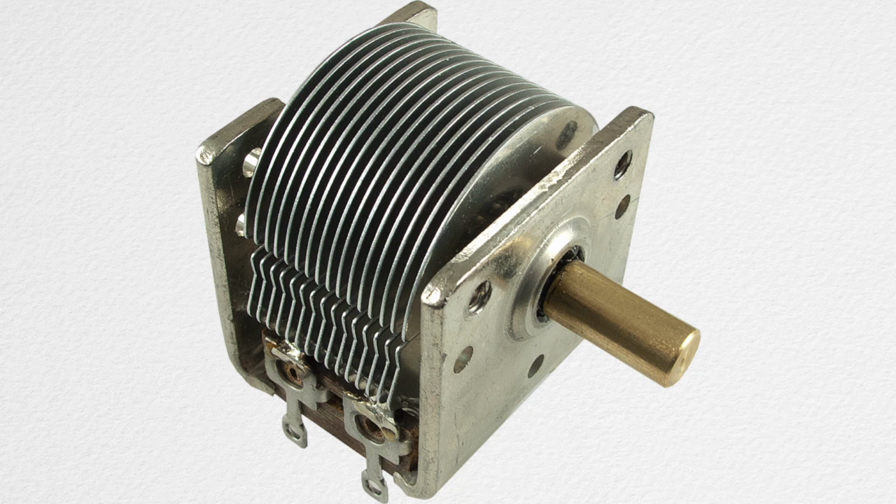This is a picture of a variable capacitor. As you can see, there's several different plates, and each one of those plates turns along with that knob. Now, there's some fixed plates in there also that don't move. Now, whenever you turn the knob, the spacing in between each one of the plates changes minutely, which changes the capacitance. These are used in a lot of tuning applications.